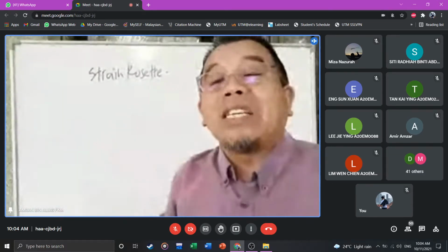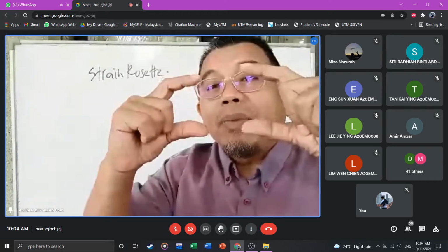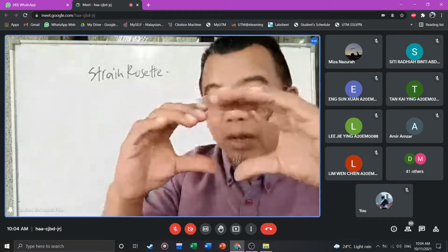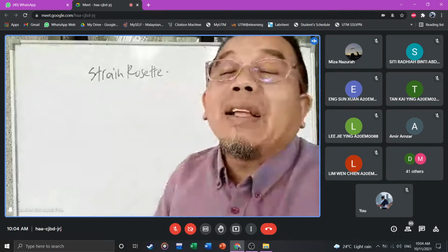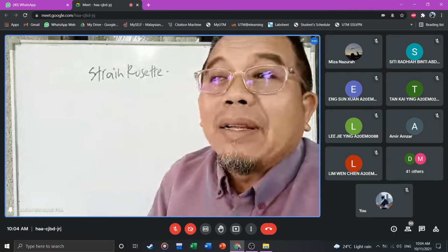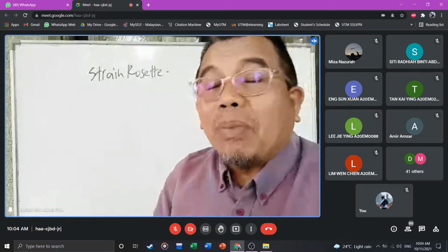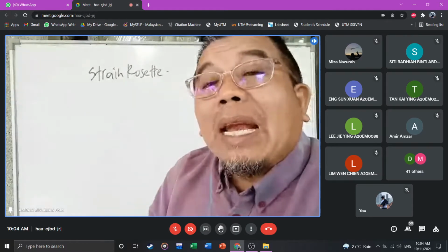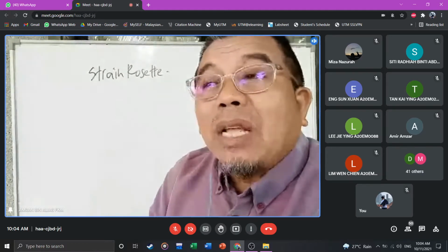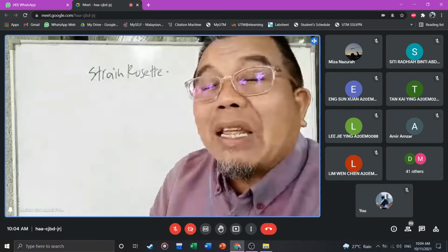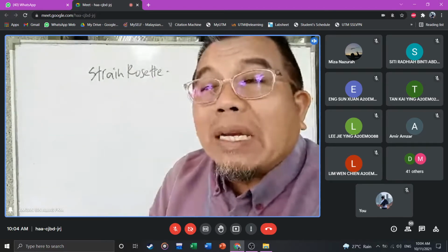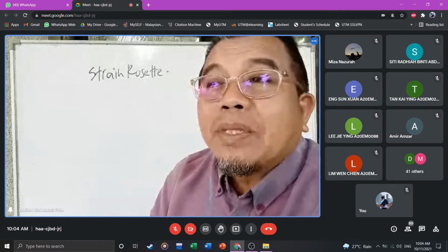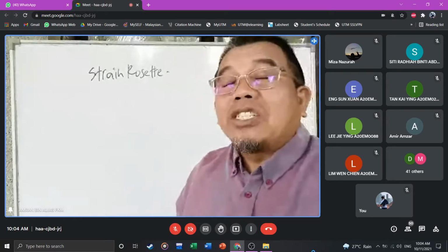And then we have the shear strain, about the shape becoming shifted to the left or to the right, or being twisted, or the square becoming like a rhombus or like a kite. So that's the effect. That is talking about the angle, how the angle deforms. Usually the angle is less than 1 degree, maybe 0.1 degree. We're talking about metal, cannot see by our eyes. How the deformation changes, that's gamma.